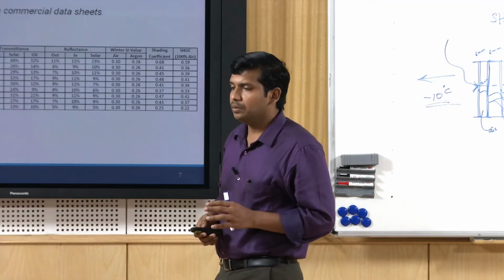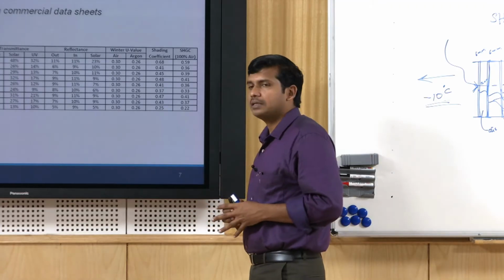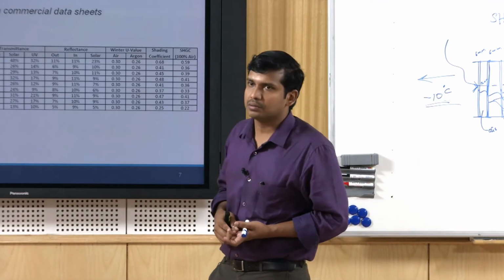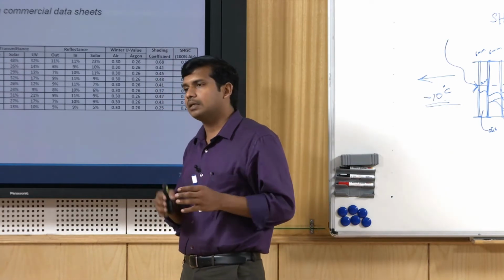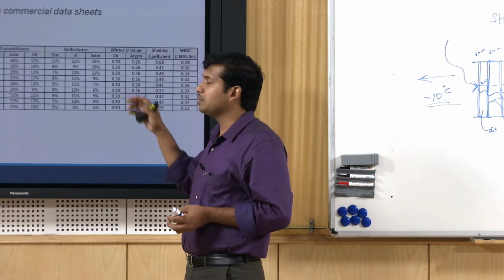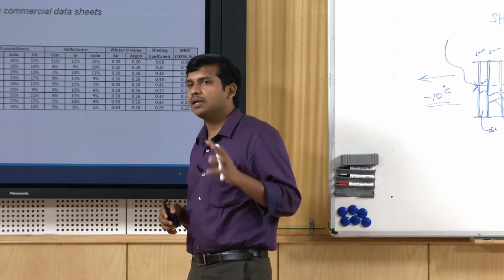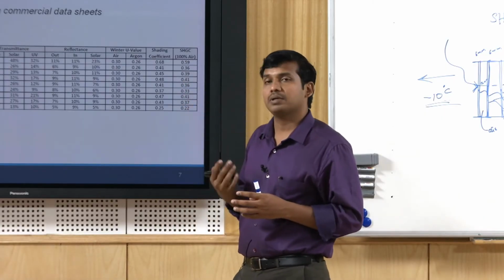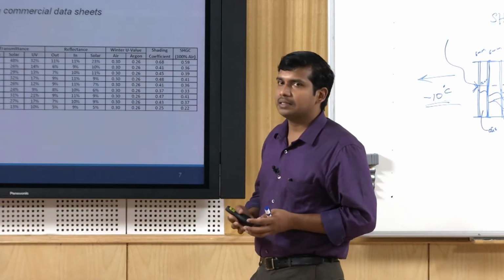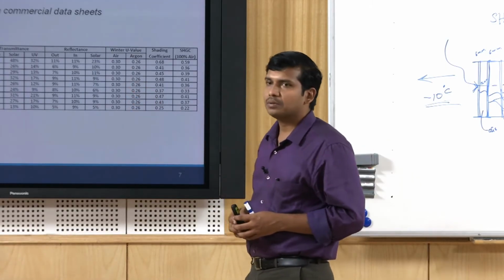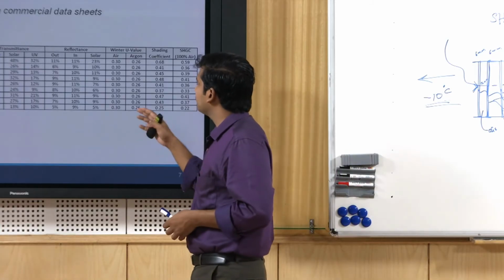When you say U value, typically you will get the NFRC, National Fenestration Rating Council of US standard tested U value. So there is a set outdoor temperature and set indoor temperature for which the U value is calculated. Some calculation procedures require you to test for different conditions also, but most of these brochures and data sheets that you get correspond to NFRC standard tested U values.